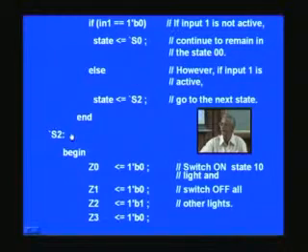Right. And suppose this condition is satisfied, we continue to remain every time the clock strikes. You come to the same route and are always revolving around the same state, right? And only if in1 changes to 1, this will not be processed, and it will go to the next state, which is S2 here.